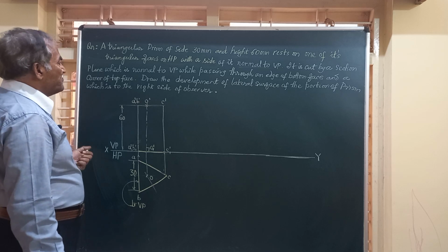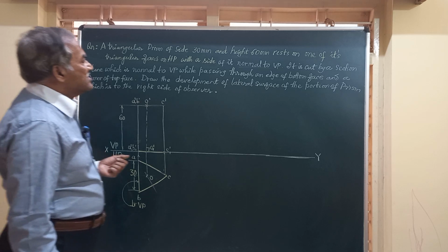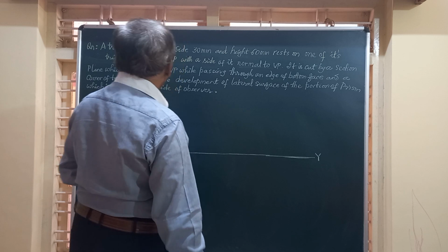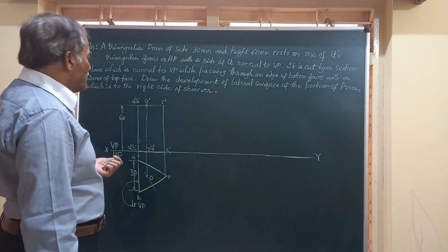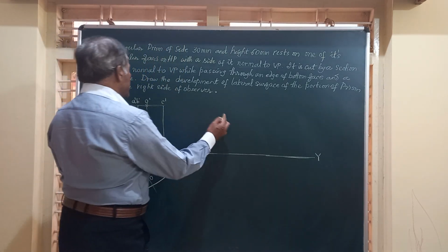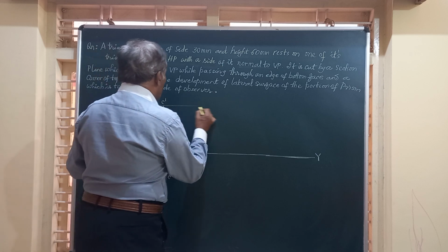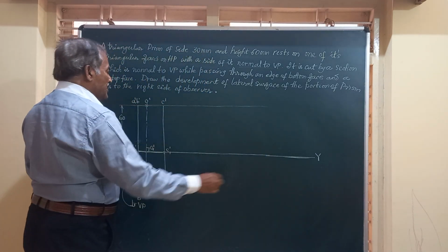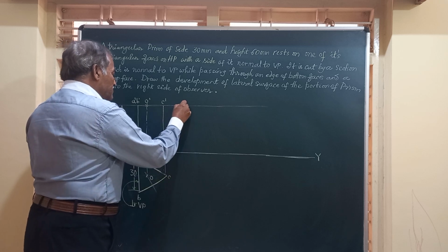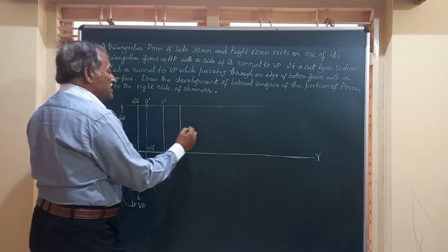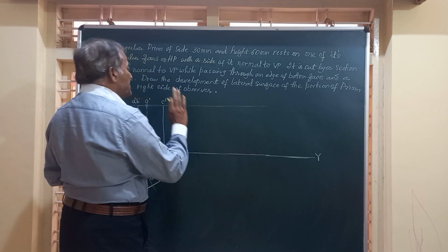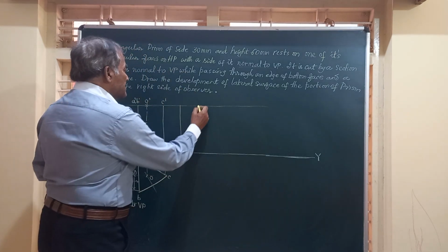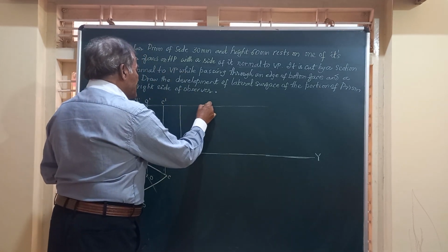Now friends, what is given in the question is, he says it is cut by a vertical section plane. So before that, friends, let us draw adjacent to this front view a rectangle which has a height equal to 60 mm. Say from here I am marking, and there will be three rectangles on the lateral surface, each of width 30 mm.